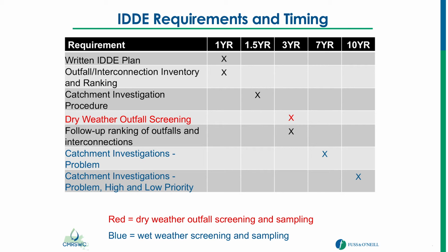So the permit gives you the opportunity to take care of those illicit discharges. You don't have to do outfall screening at those because you already know you have a problem at those. Then the high priority would be areas where you've had complaints in the past, you've had sanitary sewer overflows in the past, any place you may suspect that you may possibly have an illicit discharge; you would put those in the high category. Then you have a low priority category under that, and then the exempt ones are outfalls that you don't have to do screening for. If you have, say, a town forest and there's no sewer infrastructure that runs through the road that goes by the town forest, and you've got a couple of catch basins in there and an outfall, those would become exempt because they have really no possible way of having an illicit connection to them.